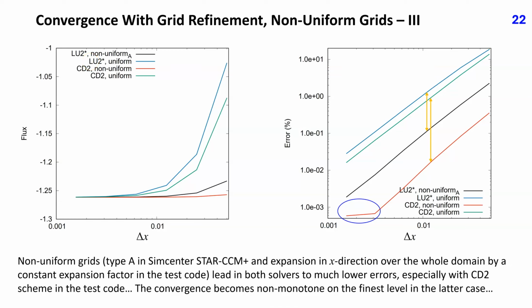In Simcenter STAR-CCM+ code, an expanding grid within prism layer is used while the rest of the grid is uniform. The prism layer on the coarsest level has 10 cells with expansion factor 1.2, total prism layer thickness is 0.125 meters. The number of cells doubles in prism layer with each refinement. The expansion factor reduces to the square root of the value on the coarser grid.